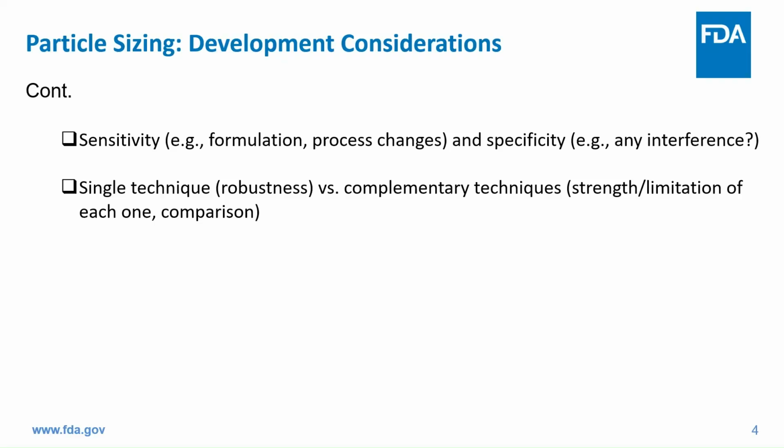And this is where complementary techniques can become really helpful, for example dynamic light scattering, laser diffraction, electron microscope if it's really small, or just a microscope technique if it's large. So different techniques provide information about the particle that we're analyzing.